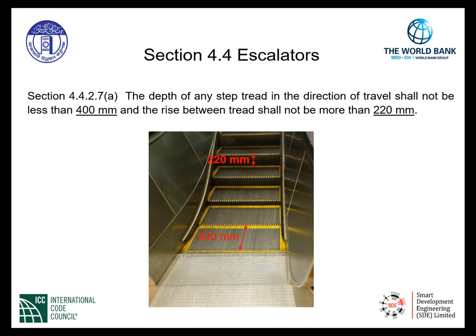We start out looking at the photo below. As indicated, we have a minimum tread depth of 400 millimeters, and we have a maximum rise between the treads not to exceed 220 millimeters. These are our minimum and maximum requirements according to this section regarding the escalator steps.